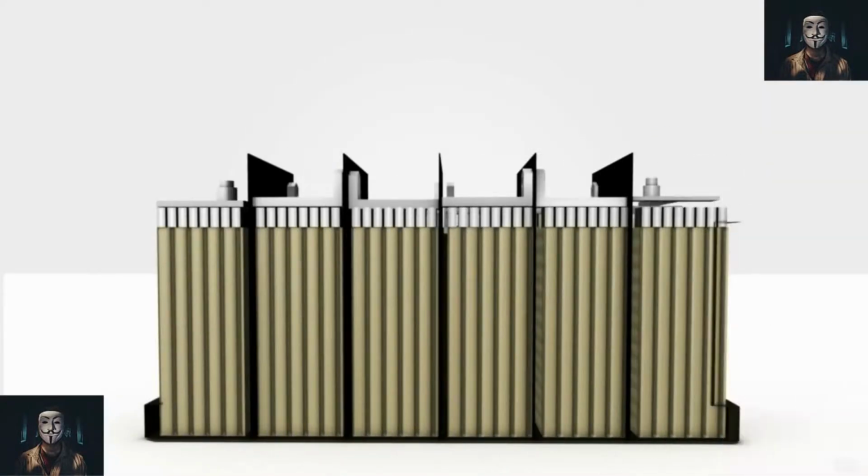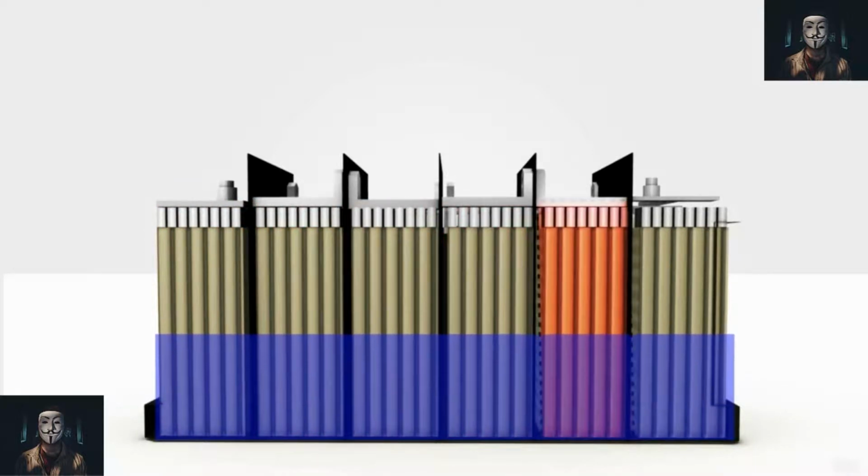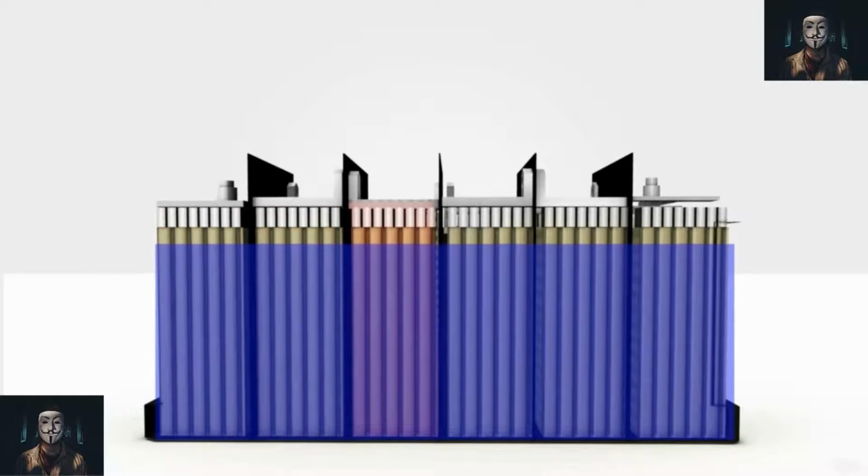1.280. The reading for a half-charged battery cell is 1.2, and for a fully discharged battery is 1.150. As most batteries are sealed, the voltage of the battery can be used to indicate battery condition. A fully charged battery will give a reading of 12.6 volts and the discharged battery 12.0 volts.